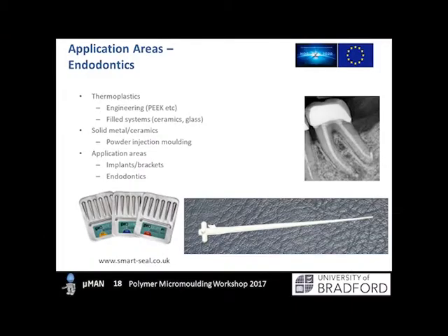Another one is dentistry, surprisingly. We've done a fair bit of work with different dental applications. This is one of those, which is the core for root canal treatment that goes down the nerve of your tooth, if you were unlucky enough to have had a root canal treatment. Basically this involved lots of development work on getting the material right. So it's a two-component nylon, heavily filled with a zirconia material. We had to look at how the material flowed, how we could ensure that the process was going to be a success. And then this is taken away, and a coating is applied to this core.